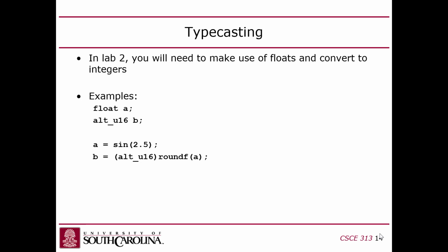Yes? In Lab 1, we didn't have the interrupt timer, so how was it able to do the time delays? Oh, that's a good question. In the original version of that lab, we did have the interrupt timer because I thought that it was required for the same reason you just asked. Like, how does it know how much time has passed, right? So I always had everyone put it in. And one day I decided to look into how the uSleep function works, the microsecond sleep. And it turns out it doesn't require the interrupt timer.